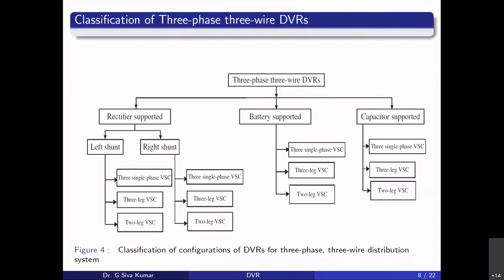Why? Because once your inverter starts functioning to correct the PCC voltage, then obviously this much amount of real power and reactive power is going to be injected into the system. If the inverter starts injecting this amount of real power, the capacitor voltage is going to decrease.